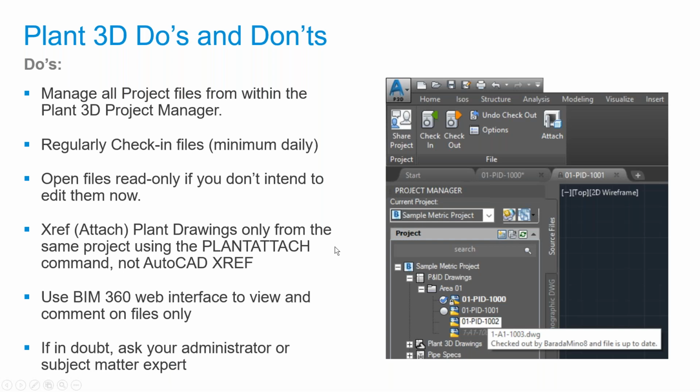And I don't remember, Joel, if you actually avoid using just the regular XREF command. Is there danger in that if you were to type in XREF and then browse all the way to your collaboration cache? I don't know if that's supported or not, or if it knows that it's doing the same thing here. Well, it'll look there, but it's not going to download it to your local workspace.